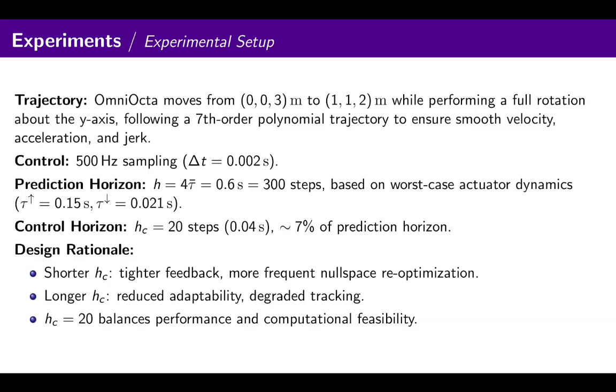This strategy enhances closed-loop robustness by limiting the influence of model mismatch and prediction error that accumulate over long horizons. Applying the optimized sequence over the entire prediction window without replanning can lead to divergence, as inaccuracies in the forward model cause the controller to overcompensate. Frequent reoptimization with early truncation keeps the controller responsive and prevents oscillatory or unstable behavior.